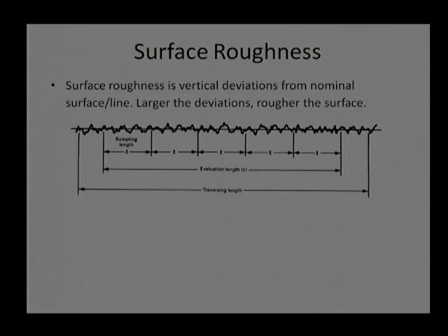We know the surface roughness is statistical. We cannot find a single value. So in that case, we average these five sample lengths, and whatever data comes is the mean surface roughness. So there will be a mean value of surface roughness as well as a standard deviation. More sampling lengths will give a better result, but will consume more time, and that is why, as per the standards, they have come to the final figure of five sampling lengths, which gives reasonably good results. That is why we are choosing this mode.